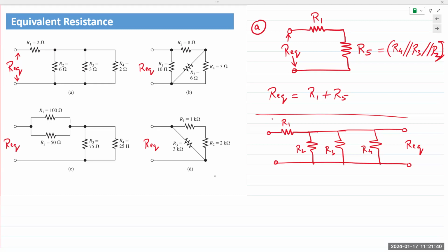What do we see? Absolutely. That answer is correct. So the answer is it would only be R2, R3, and R4. R1 is not part of the circuit anymore. The reason is only one end of R1 is connected into the circuit. The other end of R1 is open. It's not connected to anything. And because it is not connected to anything, it is an open circuit.